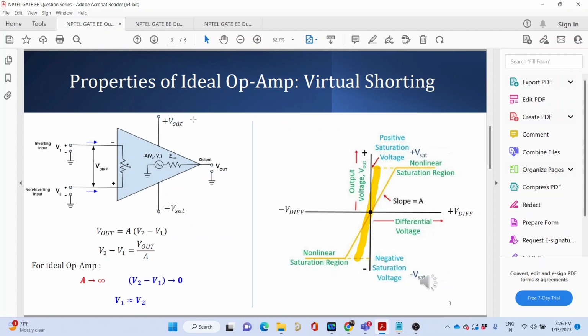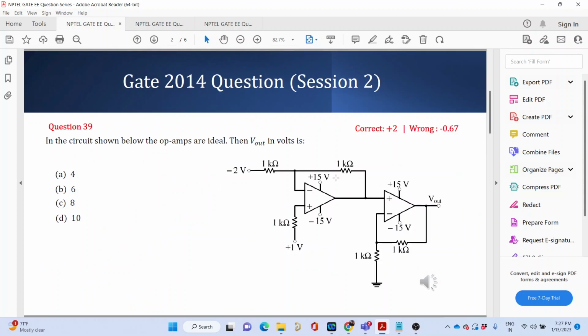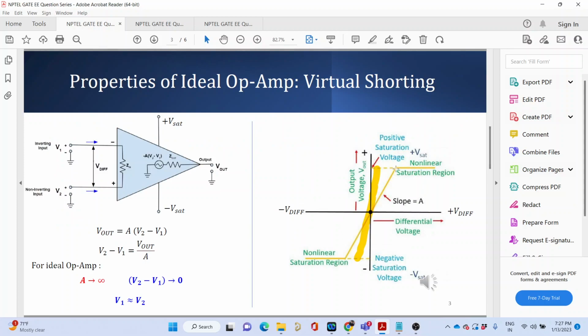Now the biasing voltage. So when you move to the saturation region, you are no longer in this linear region. When can that happen? Say you have a capacitor across this terminal and this output terminal, and you find that the voltage across the capacitor plus this voltage becomes greater than the Vsat voltage. Then you have moved from the linear region to the saturation region. In the saturation region, you cannot say that this concept is valid.